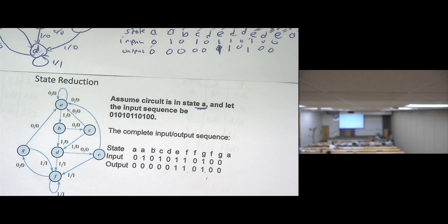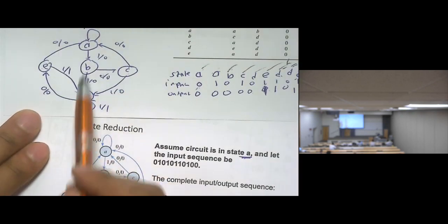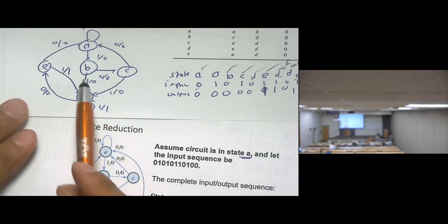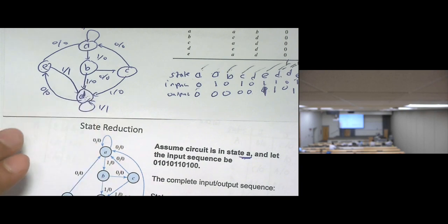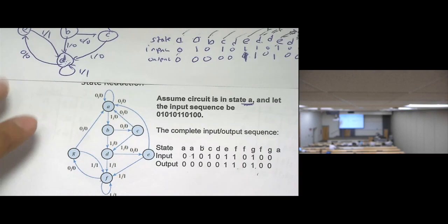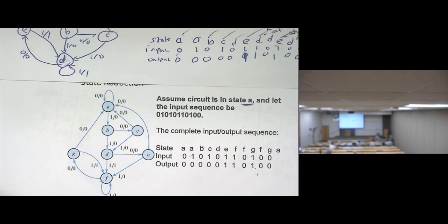So this will be large. While when we have 5 states, I still need 3 flip-flops. Sometimes, if I find a way to make it 4 states, then I need to use 2 flip-flops so I can make 3-variable Karnaugh maps. So it is just reducing the complexity, sometimes reducing the flip-flops, sometimes not, depending on how the state reduction goes.